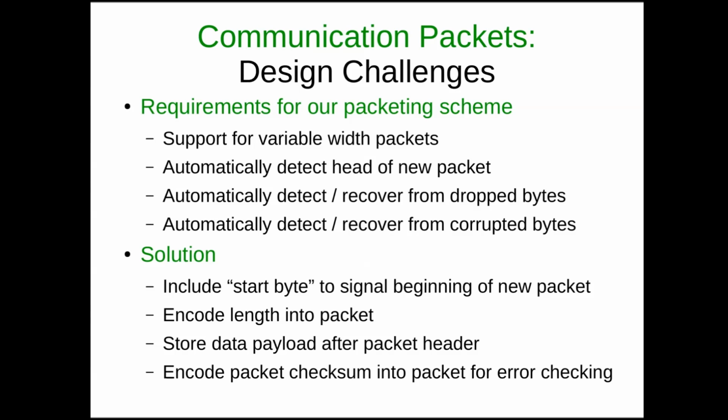So in a similar sort of situation, we may be transmitting 1 byte from our packet, but it's possible that 1 or multiple of those bits got flipped due to interference, or electromagnetic interference, or whatever. So we want to be able to detect either of those situations and understand when the data that we received from the microcontroller could be corrupted, because we don't want to control a real-world device on some communication value that may not be correct.